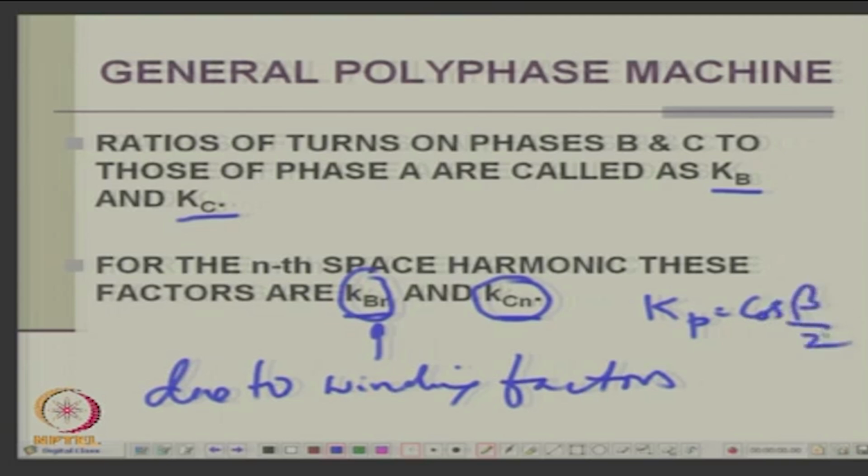fundamental, where beta is this angle between the ingoing conductor and outgoing conductor, right. That is the coil pitch, beta we call it as a coil pitch. These are from your earlier courses, you must have done them. Now, the nth harmonic will be cos n beta by tau, is it not. Similarly, distribution factors, right. So, that is why these factors will come into the picture.